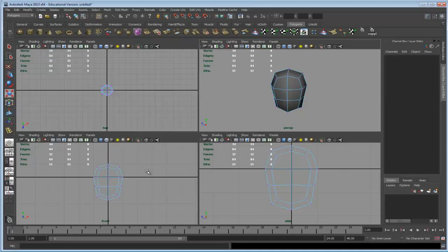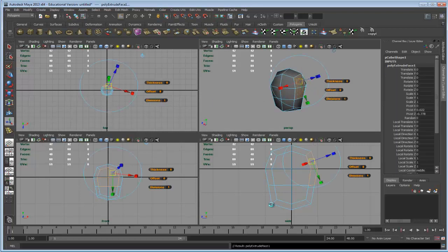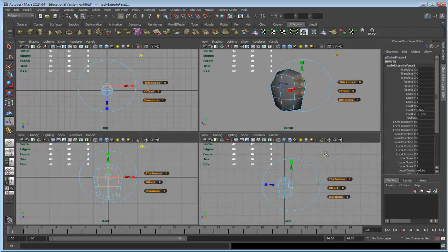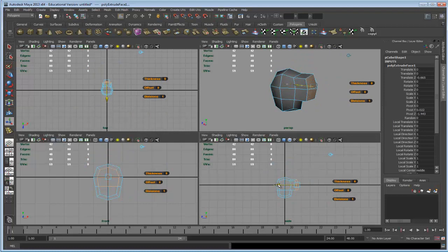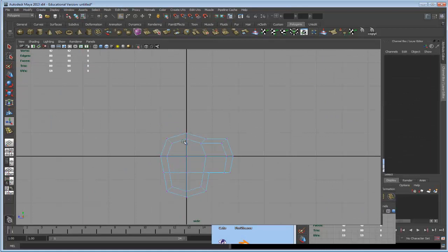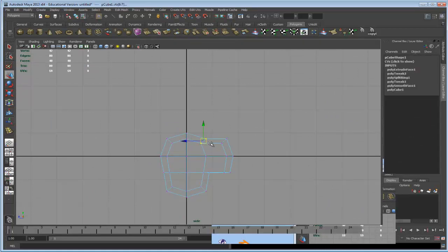So let's go back in, so we will select in the side view 2 faces at the back, which is actually 4 faces, you see. Hit the extrude button, and then in the side view just select to move by plane and move the plane out, and then we will go in and just add a little bit of shaping to the actual mesh.